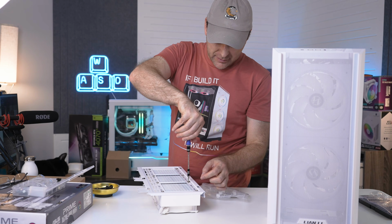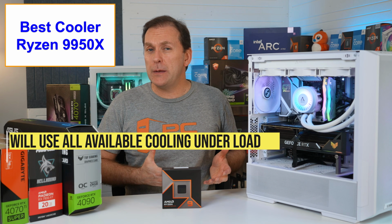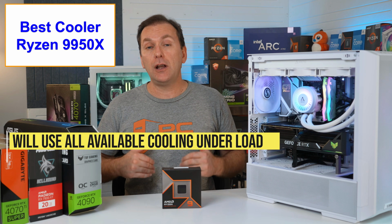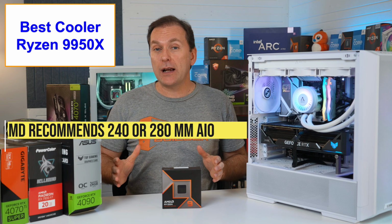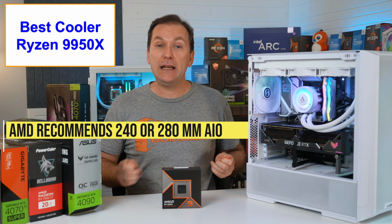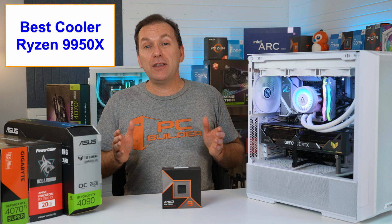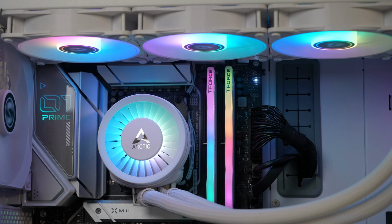Now let's talk about the best CPU cooler for the Ryzen 9 9950X. Like Ryzen 7000 CPUs, the new Ryzen 9000 CPUs are designed to use up all available cooling under load to increase clock speeds and just give you more performance. Now, AMD recommends a 240 or 280 millimeter all-in-one liquid cooler, and not only do I agree, but given the falling price of AIO liquid coolers, I'd honestly go with a 360 millimeter myself.